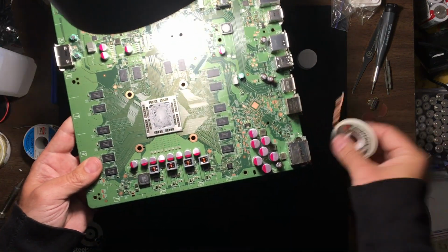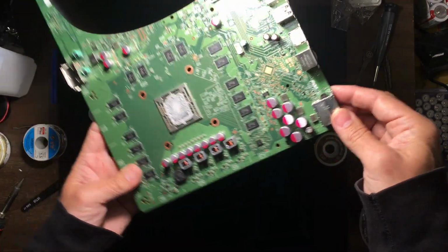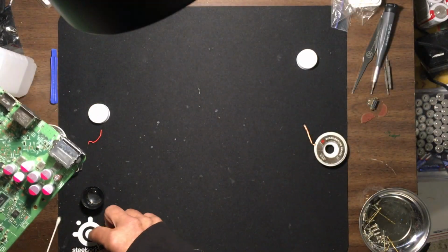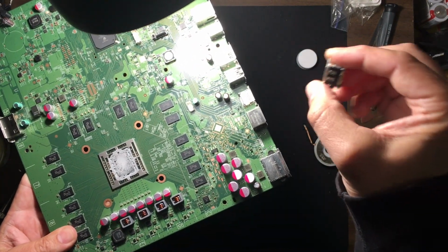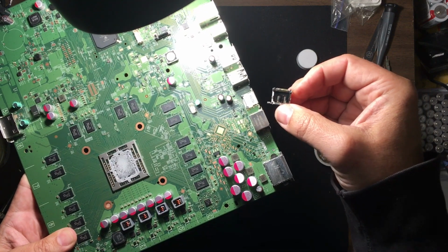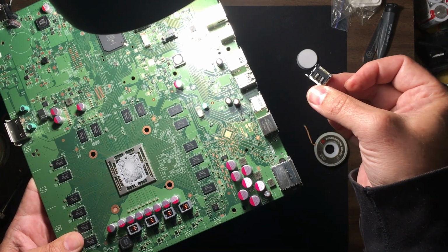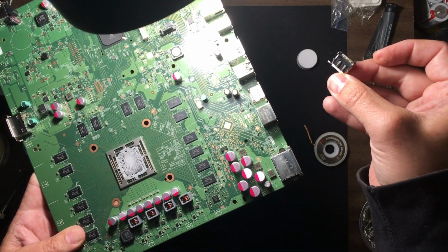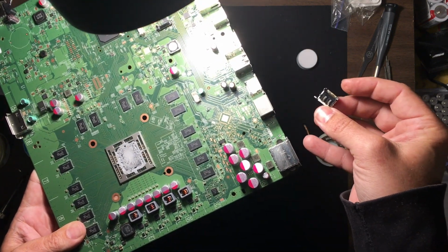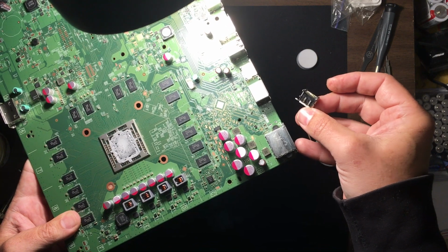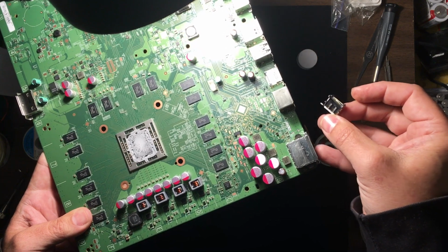So I do have just the smallest amount of solder on these points, and I have all the holes cleared out. On the actual new port that I'm going to be adding, I put some flux on here, ran a little bit of solder across that as well, just the tiniest amount, and then cleaned it and put a little more flux on again. So I'm not going to add any more solder to these two sides. There's already solder. They're both tinned basically on both sides, so they should have enough solder to hold. You don't want much anyways. It's a very small connection. You just want them to make connectivity.